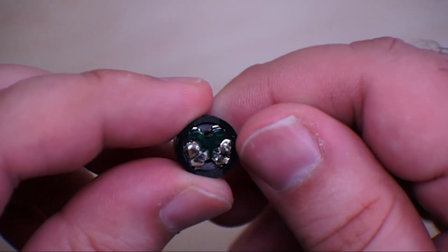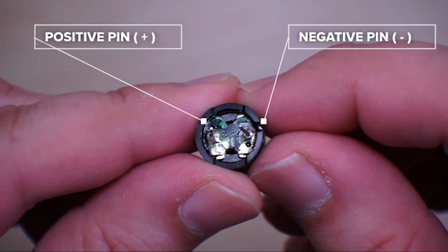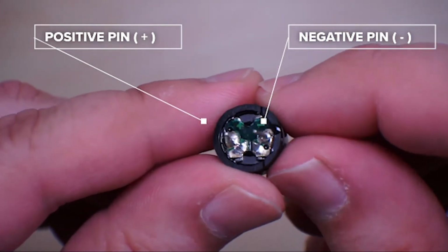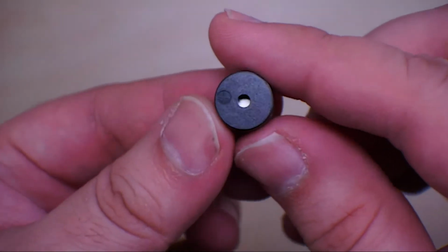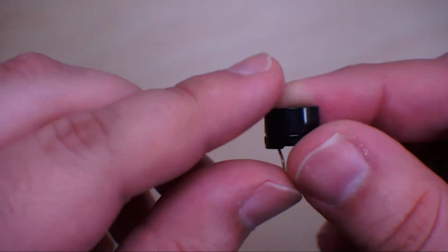The Piezo Buzzer is polarized, which means there is a positive and a negative leg. To see which leg is positive and negative, look for the positive and negative sign underneath the Piezo Buzzer. You should also notice markings on the side of the Piezo Buzzer that also indicate which leg is positive.